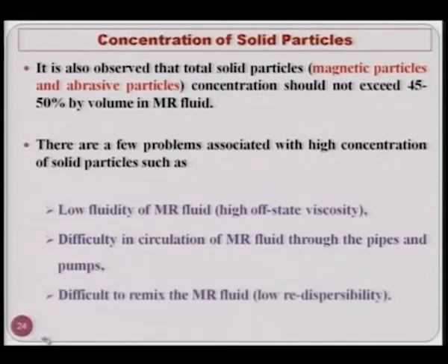It is difficult to remix the MR fluid, that is, low redispersibility, because once the magnetic field is removed, the particles should be easily dispersed in the medium. That does not happen if the solid particle concentration is more than 50% or so.